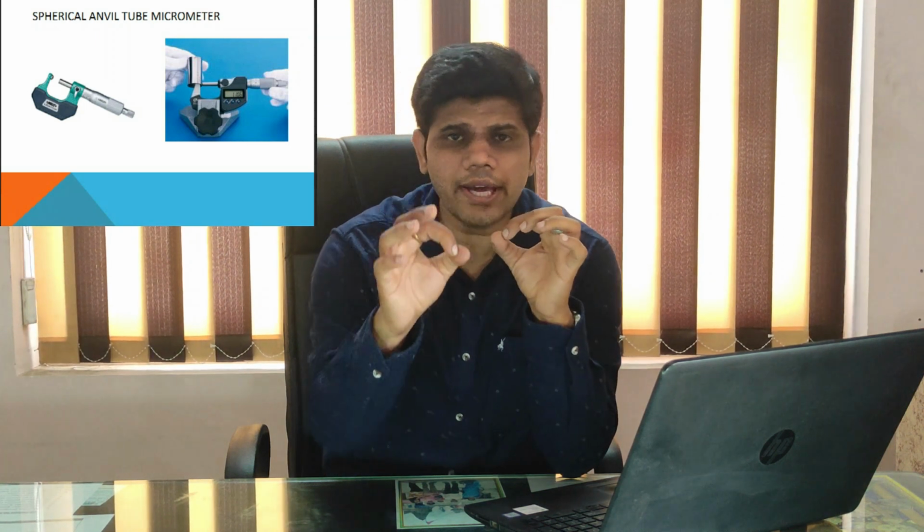The next micrometer is the crimp height micrometer. It is very unique and very less used, but it is really important for those in the electric cable industry, I mean those manufacturing crimps, which are generally used in motors or vehicles. If you can see in the presentation, the crimp is straight on one side and flat on the other. The flat portion, the sharp portion, will hold the crimp, and the other portion, which is pointed, will get into that crimp and give you the exact diameter, the length of that crimp. You can see it clearly shown in the display.